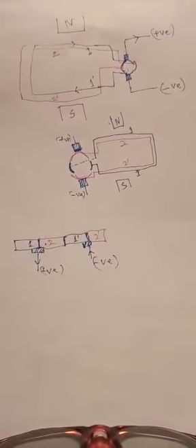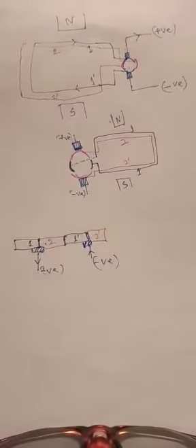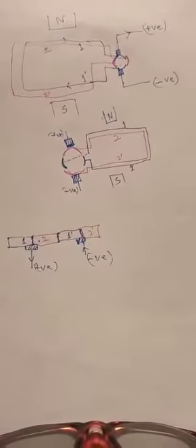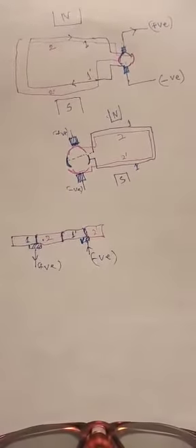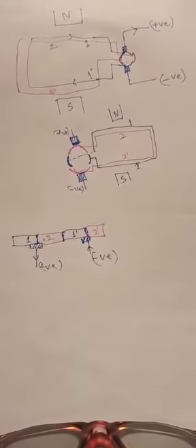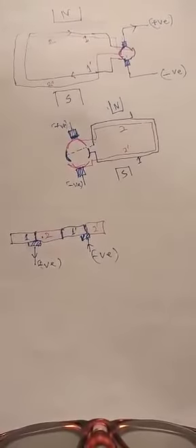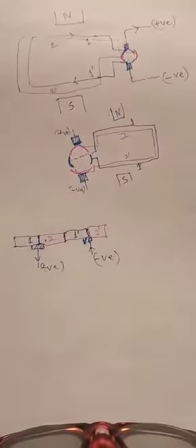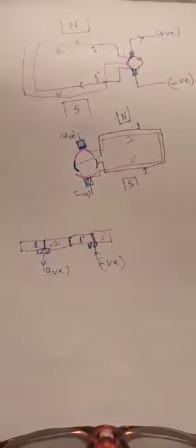As you know, in case of a DC machine, the losses are mainly frictional losses and windage losses, which are a kind of mechanical loss, then air gap flux leakage, then armature voltage drop losses, armature reaction losses, and brush drop.